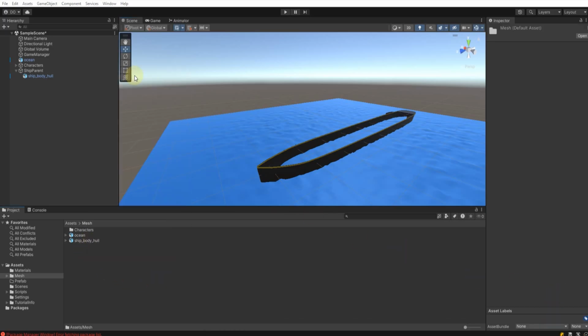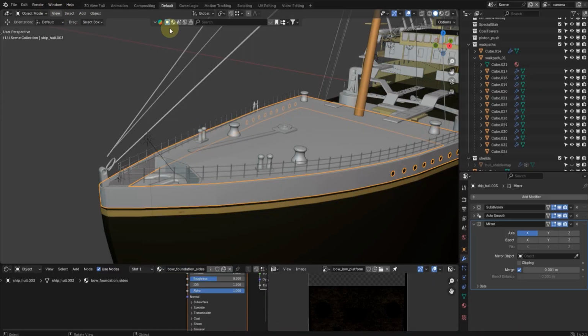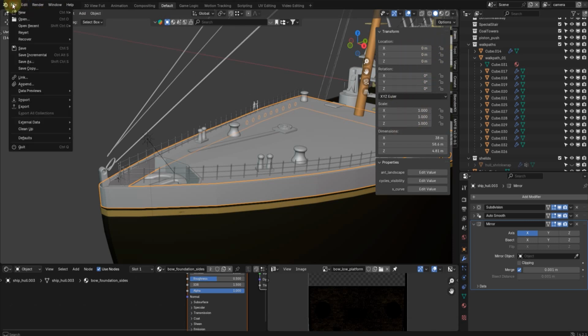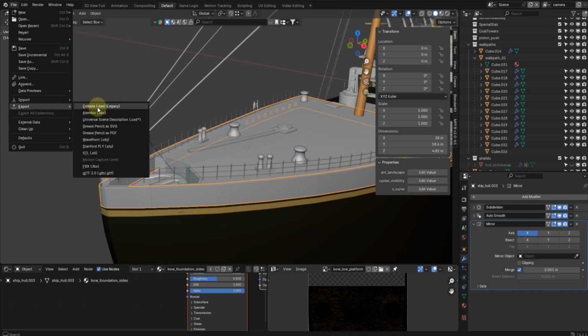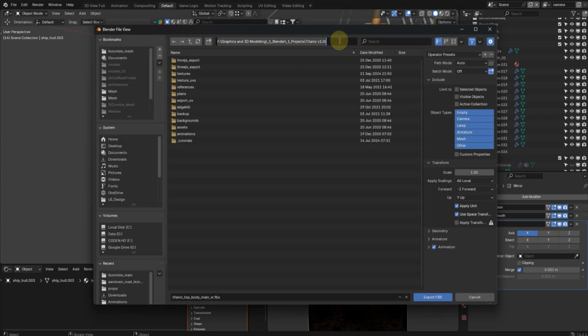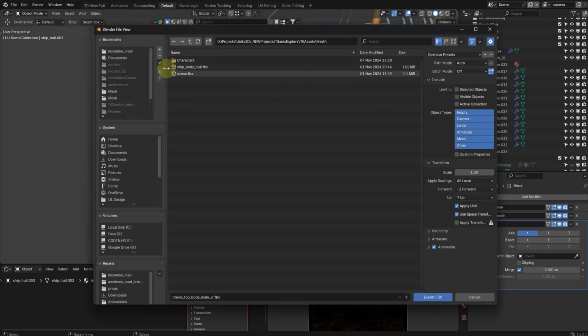So I'll look at the bowl and try to export that. What I'll do is go into Explorer and locate the folder of the Unity application's mesh. Then I'll copy the link and go back into Blender, and then I can export this model. First of all, I'll check the transforms, make sure they're all applied, and I'll go to File, Export, FBX, and then paste in the mesh location.